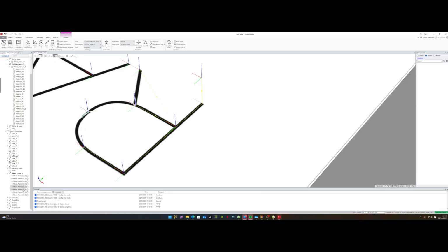So you select the two of them, right click on it, you should see modify instruction, convert circular, move circular, and now it's going to move circular. Okay, now it will move circular from here to here. Now remember, we're going to move linearly over here to target 60.